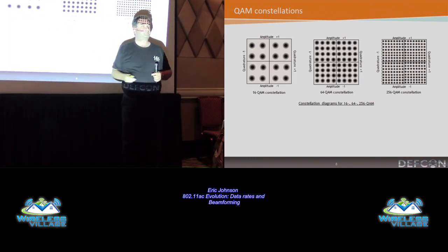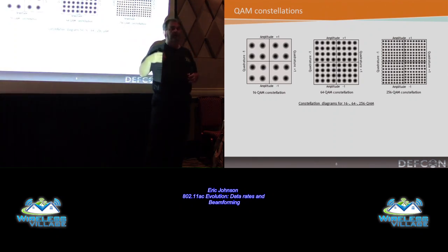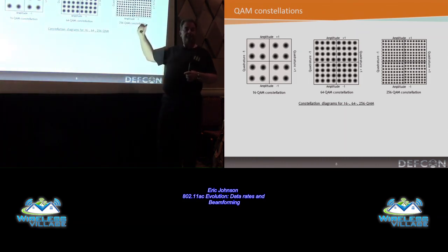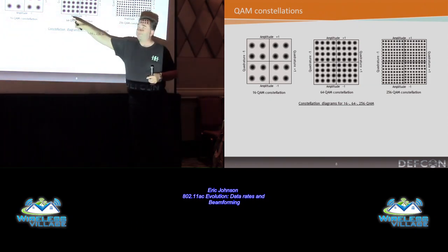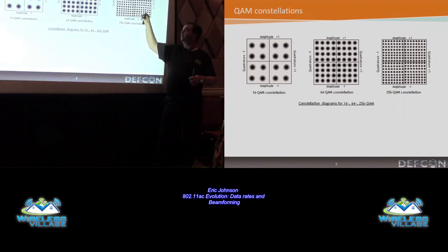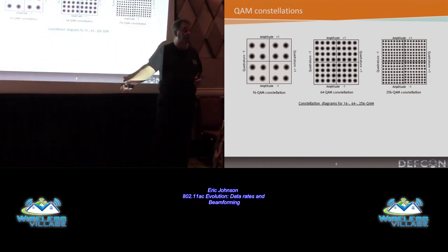Okay, so this is one of the things that's confusing, because I get numerous questions from people in the Wi-Fi business. Well, they go, okay, well, 64 QAM, 256 must be 4 times better. It's not actually, right? That was 4 bits, this is 6 bits, and this is 8 bits. So for each burst, I'm only getting 2 more bits across here compared to here. So it's 33% better, which I'll take.